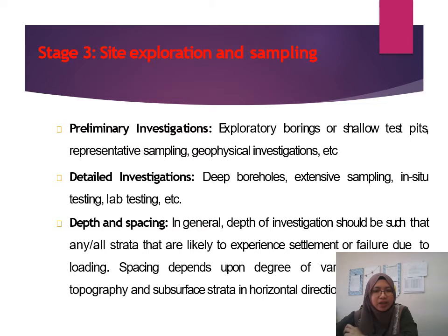Detailed investigation is deep borehole, extensive sampling, in situ testing, and lab testing. Deep borehole means that you have to advance the process. For preliminary investigation, it is not too far from the ground surface, but for detailed investigation, you have to go into detail, you have to advance the borehole. And then depth and